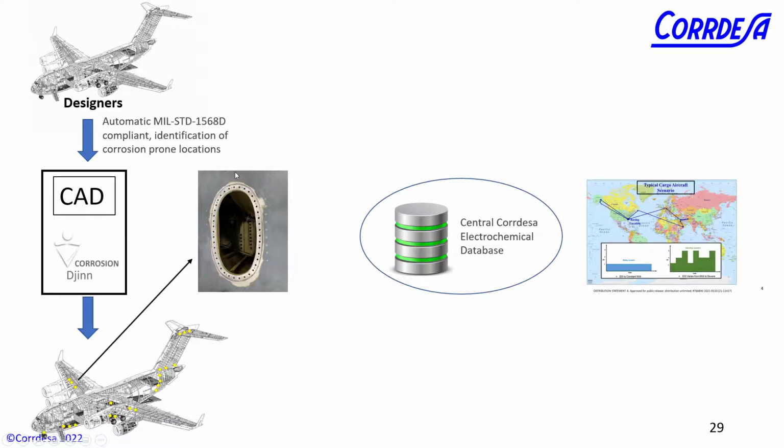But even now, we can still run these kinds of calculations, because as we do sustainment, materials change. As I've mentioned before, you can't use cadmium. You may have to replace it with zinc nickel. What is the impact of the new coating on my system when I coat these with zinc nickel and send them out again? So you can use this in design or sustainment.